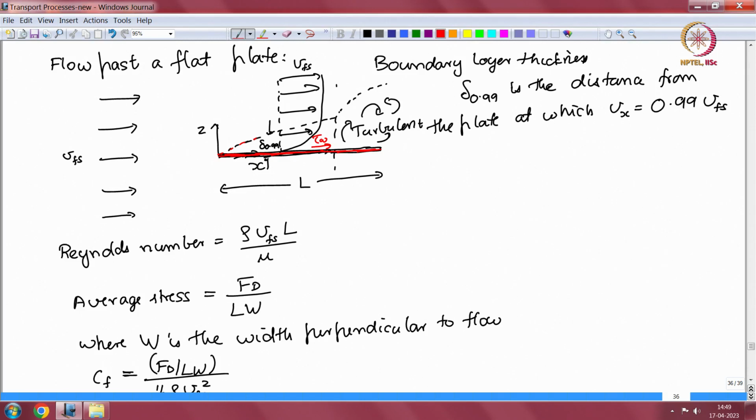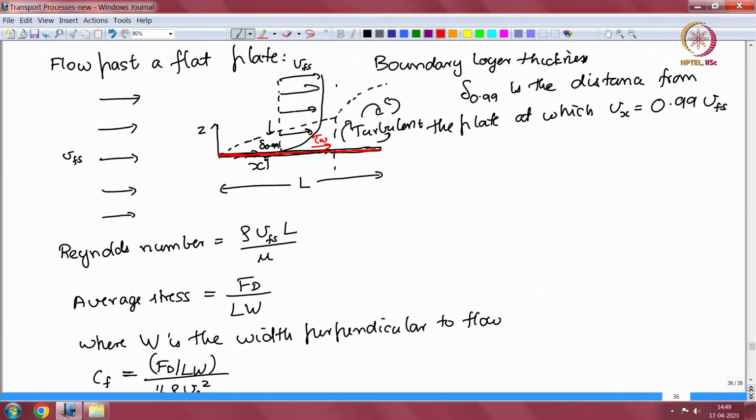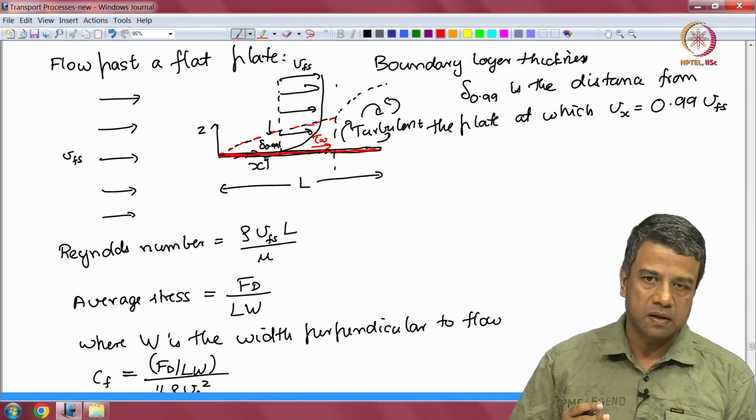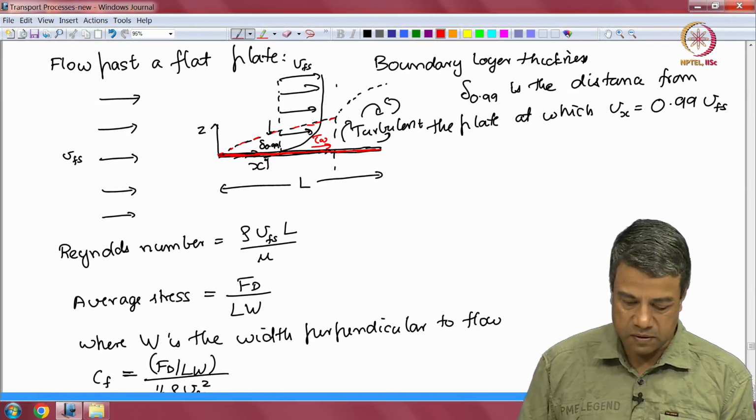So, in this particular case, you have a flat plate with virtually no area projected perpendicular to the flow. Therefore, there is very little deformation of the streamlines around the surface. You have a free stream velocity far upstream, and as the fluid goes past this plate, there is a retardation of the fluid due to the presence of the plate. So, most of the force exerted on the plate is due to the shear stress on the surface parallel to the velocity and not on the surface that is perpendicular, because that projected area is virtually 0.